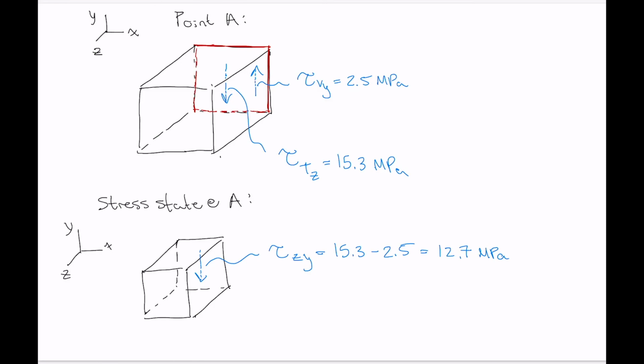And then we're not done yet, because we show the complementary shear stresses here. So we've got 1 shear stress on that face that acts upwards, and a shear stress on the top that acts like that, and 1 on the bottom face that acts like that. So there's the answer to our question now. So we've got that picture with that one stress that's labeled with the magnitude and correct direction. So now we've defined the stress state at point A.